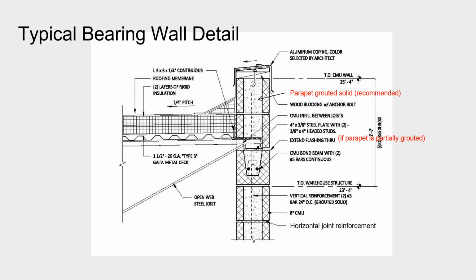Looking closely at the top of wall detail, we see it has a bond beam. On this detail, the bond beam has a solid bottom. So one detailing improvement that is essential is to provide an open bottom to the bond beam rather than the closed version shown to allow the vertical reinforcement to extend through without having to core the units.